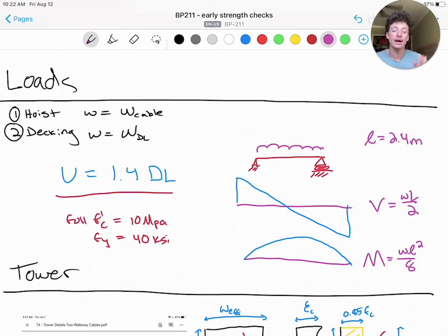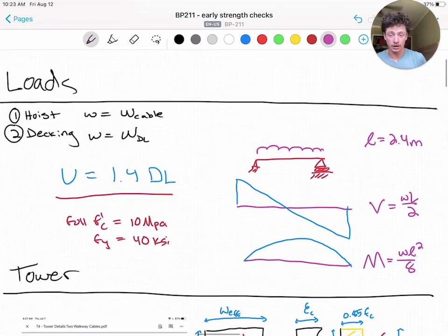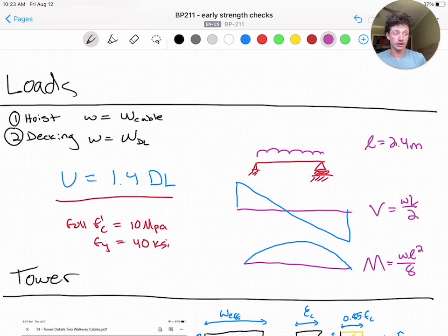So note that the bearing of the anchor onto the ramp wall is governed by the strength of the masonry walls, remember? And that is checked in previous sections, discussing those masonry walls in the component design unit about ramp walls. And it's also important to think about the bearing and axial capacity of the tower. This is something we don't even check at all, and we would think this would be more susceptible to failure with lower concrete compressive strength.